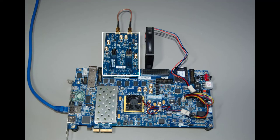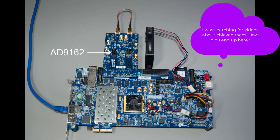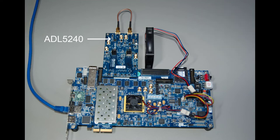The FMCOMMS11 board consists of an AD9162 DAC. This is a one-channel 16-bit DAC with sample rate up to 12 gigasamples per second. There's an ADL5240 amplifier and step attenuator in the transmit path.